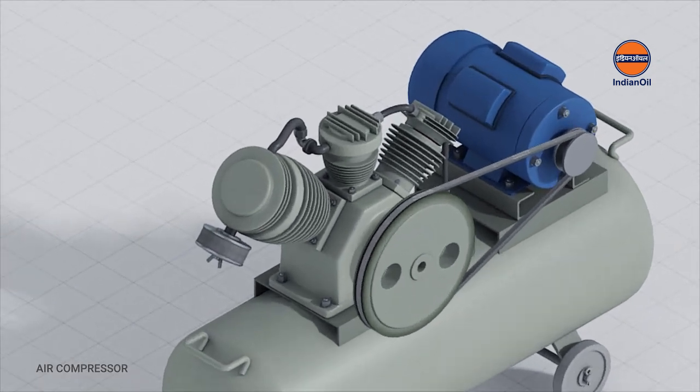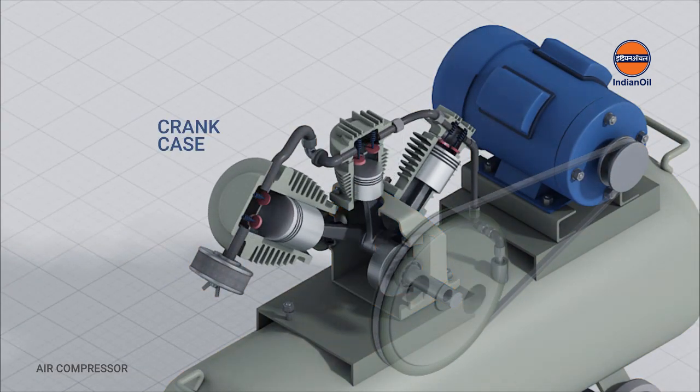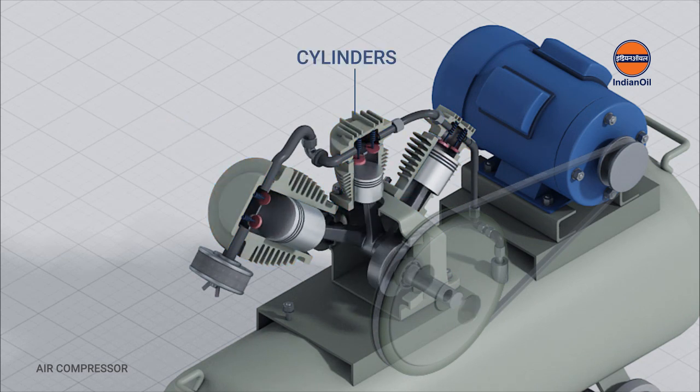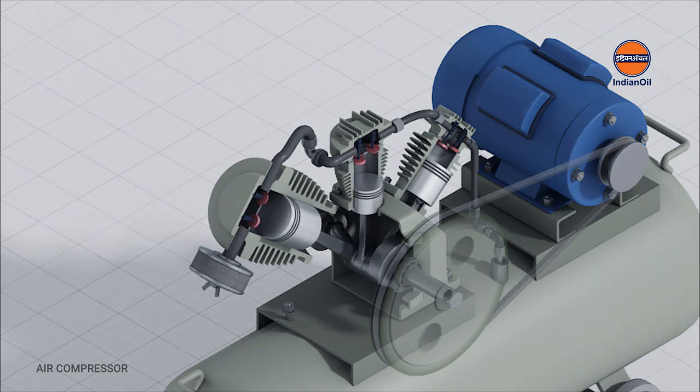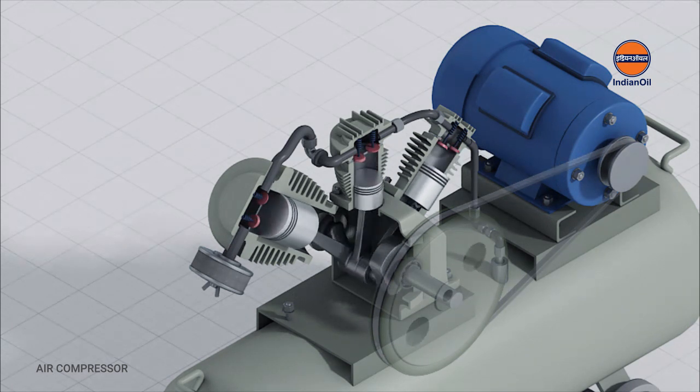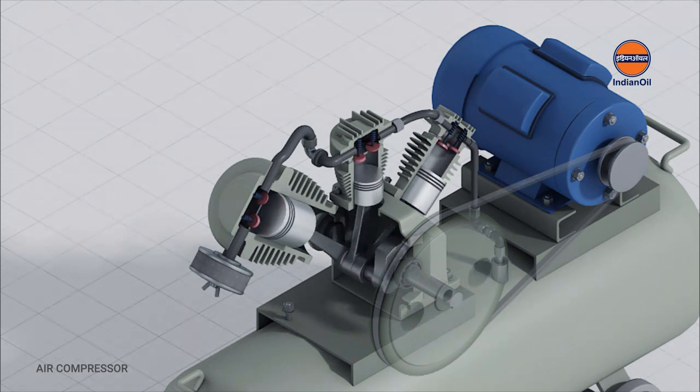The major components of this compressor are: Crankcase. Its role is to offer support to the crankshaft. Cylinders. Cylinders are pressure vessels that contain the gas that is to be compressed, and as such, they are one of the most important components of a reciprocating compressor. Cylinders support the discharge valve plates and suction, and sometimes feature replaceable liners or sleeves, which give the cylinders a renewable surface. The function of multiple cylinders in reciprocating compressors is also to cool the temperature of the machine during its compression cycle, which tends to generate heat.